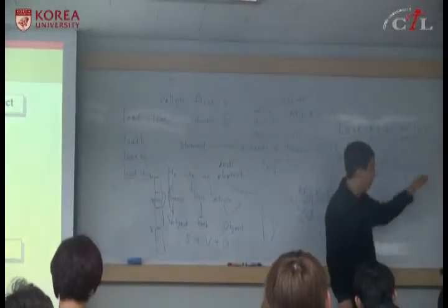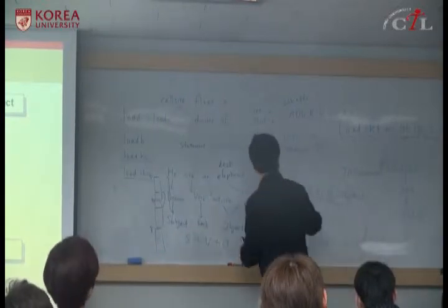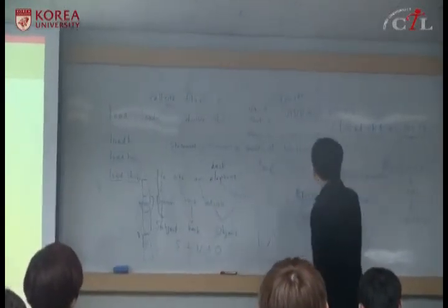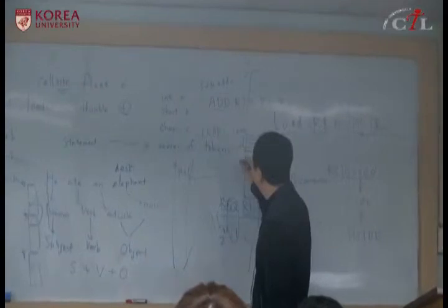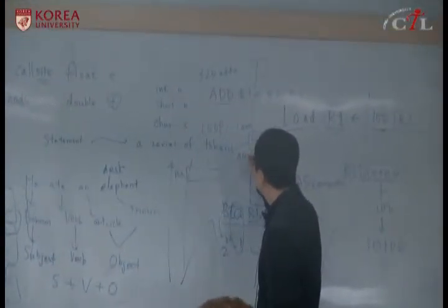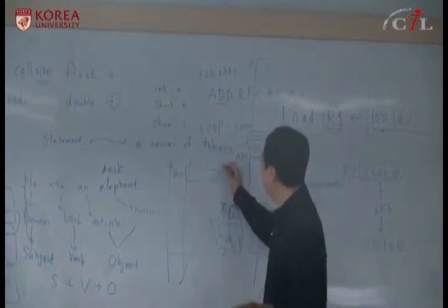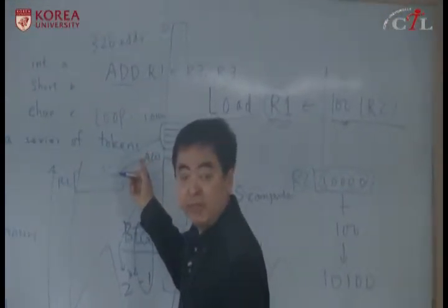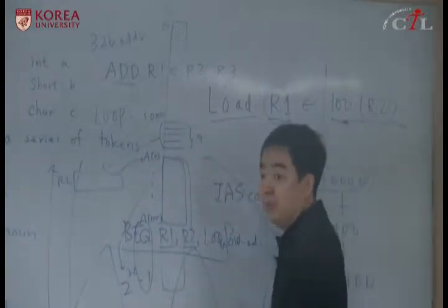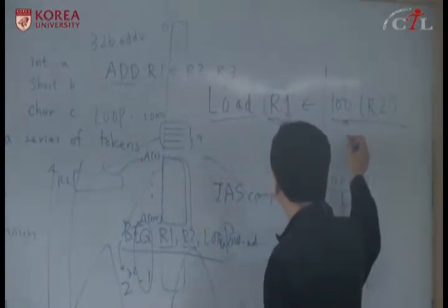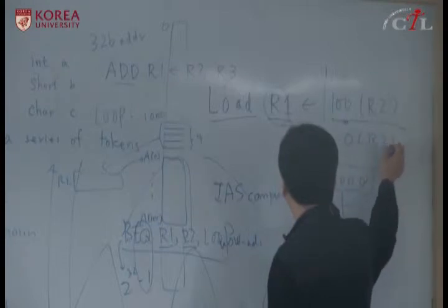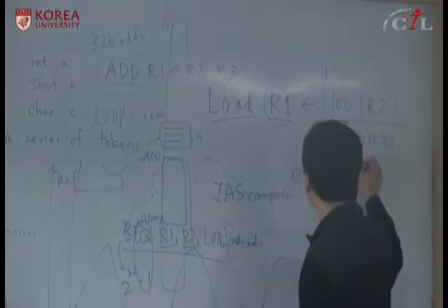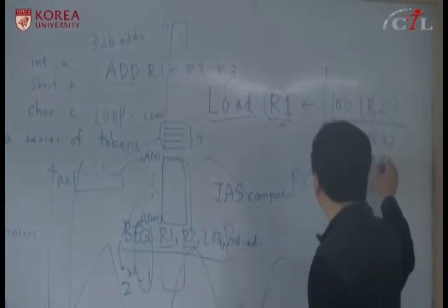What they're doing is, you can store in memory, maybe there is an array called A, from A0 to maybe A100. Right? The base starting address of this variable A, you can store into register R2. And A0 can be referenced by 0(R2). A1 can be referenced by 4(R2), and so on.